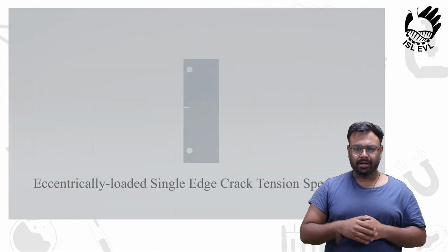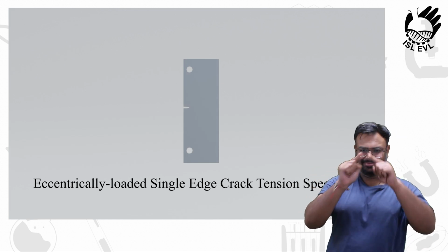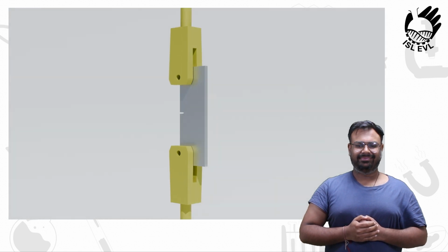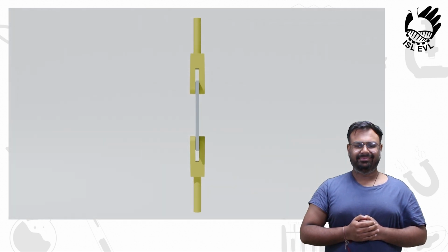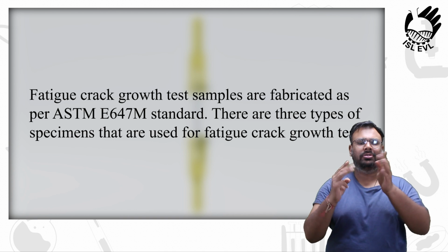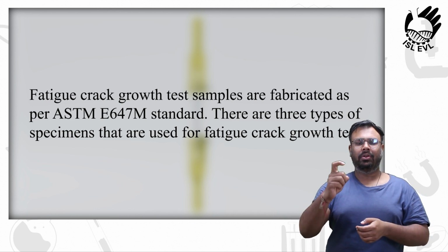Specimen. Eccentrically loaded single-edge crack tension specimen. Fatigue crack growth test samples are fabricated as per ASTM E647M standard.